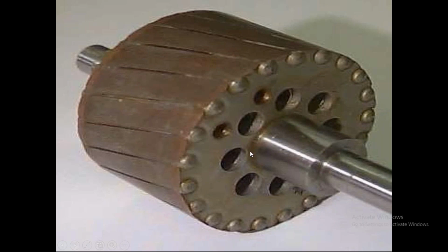So this is the visibility, and what do we call these holes, and what is the purpose of these holes? See, I already told you, in the rotor we are providing these, right. It is used for the cooling purpose, and it is called air ducts. So the holes which are provided on the rotor, we call them air ducts, and the purpose is for cooling. Okay, now are you clear on the squirrel cage? So how will it be structured?